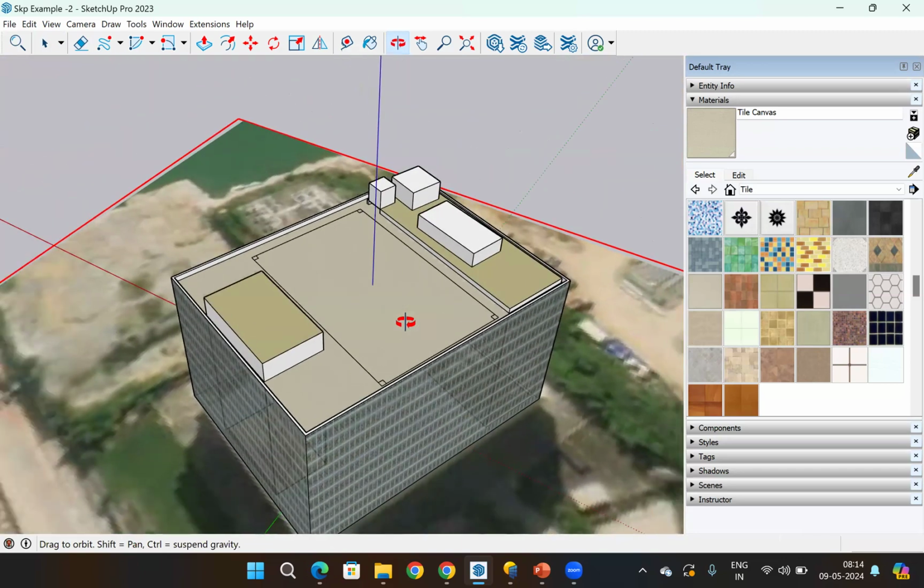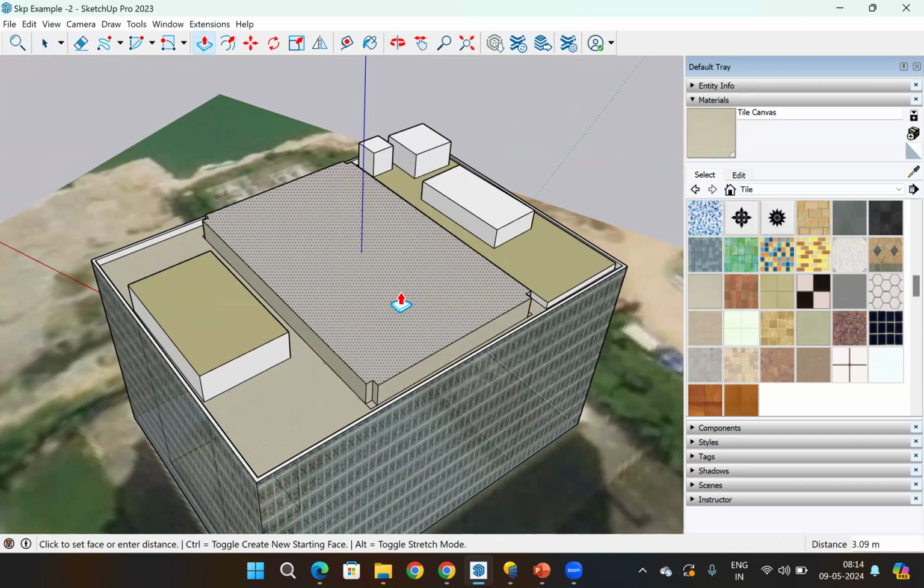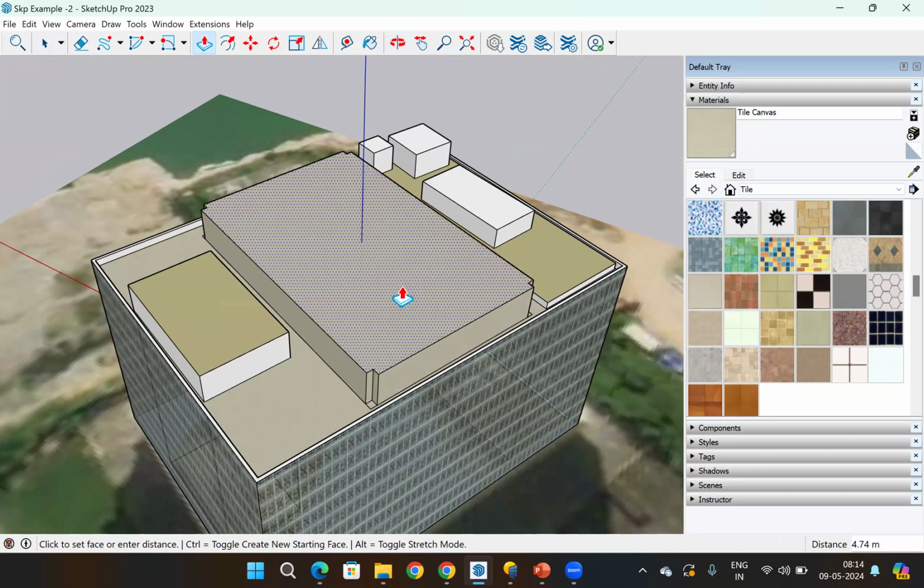So what I will do, first extrude this to a certain height. Generally cafeteria height will be around, let's take, it's sloped. Generally these cafeterias and our solar also should have some slope so that rainwater or module cleaning water drops down to one area.